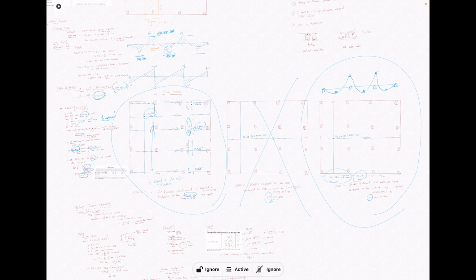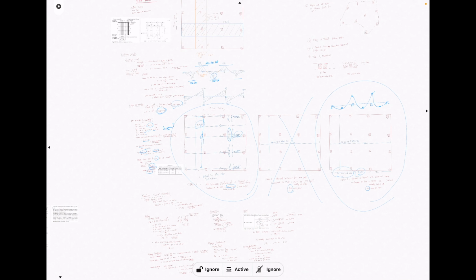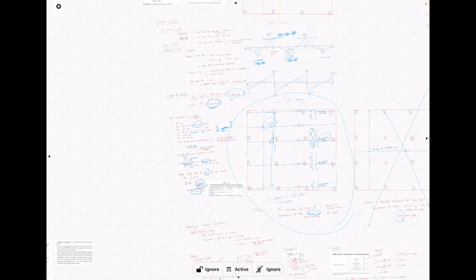And we shouldn't be designing floors for construction that have more than 30 to 40% extra reinforcement than what is required, just to maintain our sustainability goals as professional engineers and our responsibility towards the environment as well, because this additional reinforcement is not really easy to produce and it's not sustainable, so you have to be very mindful of the resources we are using in construction.